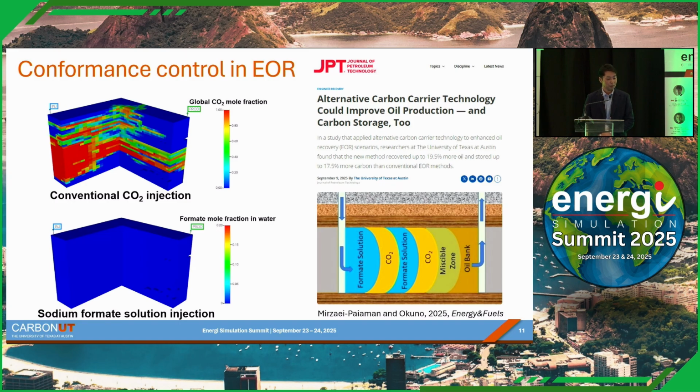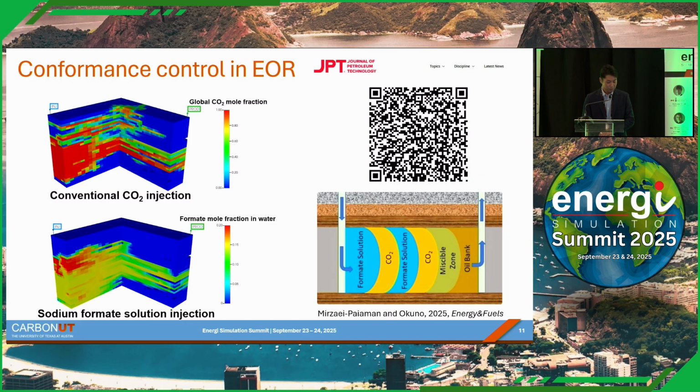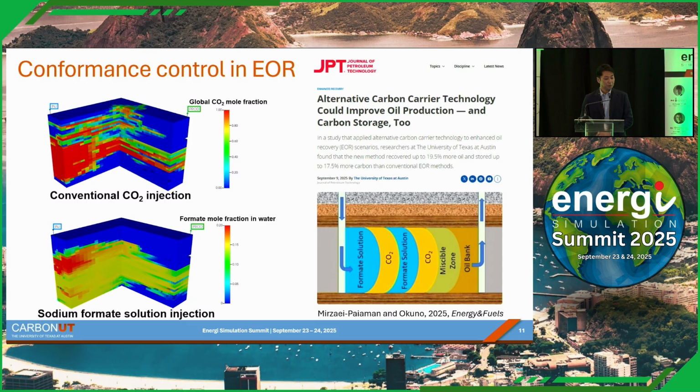So therefore, the oil displacement process is much more stable when we displace oil by aqueous media like a sodium formate solution while carrying carbon. Some of the results in our recent formate research were featured in the most recent JPT article on the right side. So in this particular paper, we compared 3 cases.